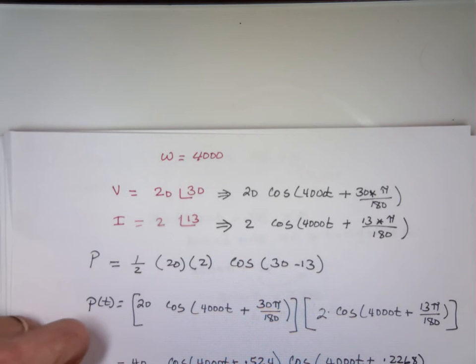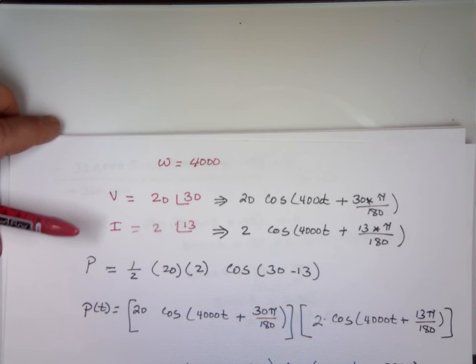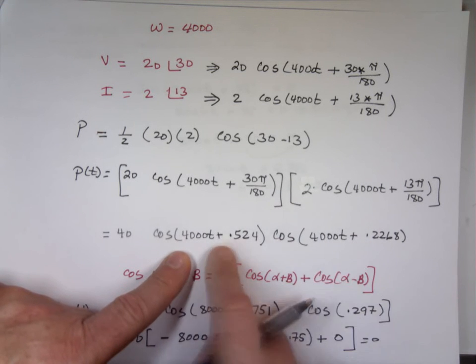It doesn't matter if it's in phase or not in phase, because if it's in phase, these two will be the same, so I don't have to use a trig identity. I can just square that, take the square root of it. But for maximum power transfer, do we really need to consider the time? No, because you asked me for it. That's why I answered this one. You asked me what's the maximum power transfer, so you don't want the average. So I had to derive that for you. So if they're in phase, it's non-time dependent, but if they're out of phase, it's time dependent? No, there will be both. For instantaneous power, both will be time dependent. Because you still have to take this and square it. It's still going to be a function of time.